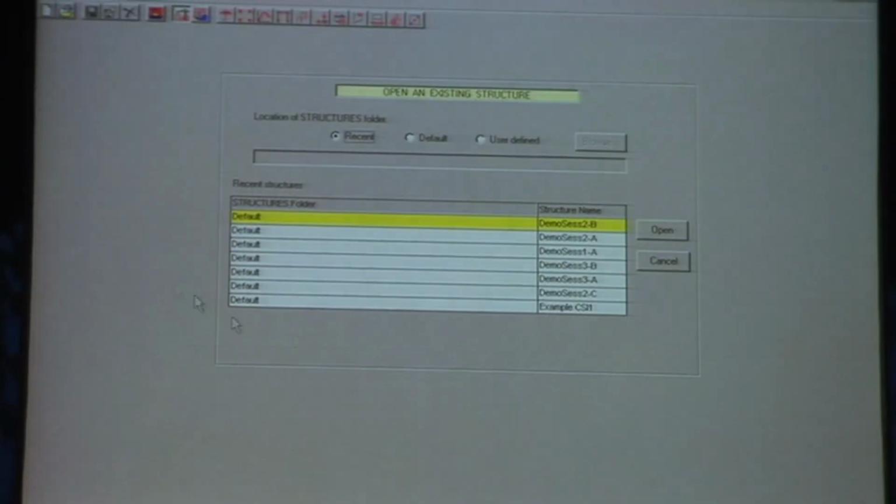So I did a third analysis here, and what I did was I took the beams and I put in axial releases in the beams, so that even though they were restrained by the rigid floor diaphragm, they could have zero axial force because they had an axial release. And I'll do that by looking at a third model.